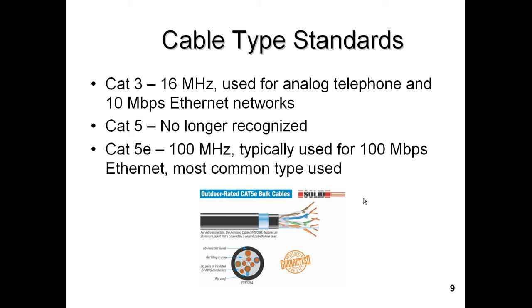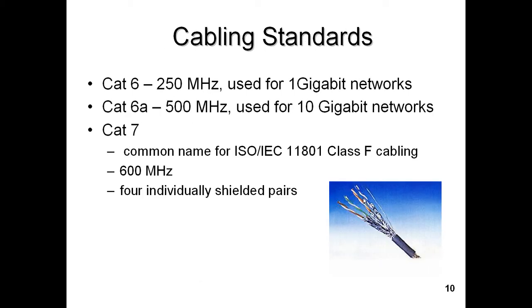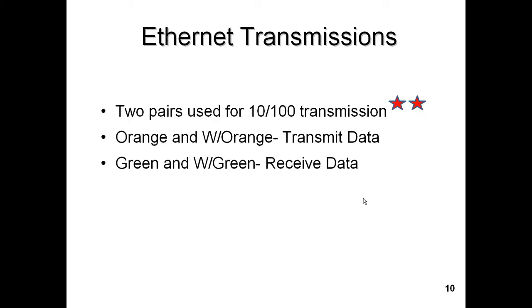You know, that 12 megabits can easily go through a 100 megahertz cable, can easily go through a 100 megabit Ethernet connection. So as long as the cable's done right and as long as the connectors are done right, you're going to be okay with Cat 5e. Now, if the customer already has Cat 6, Cat 6a, or Cat 7, you can use that cable if it's available. That's okay, but you don't need it. That's the important point I'm trying to make.